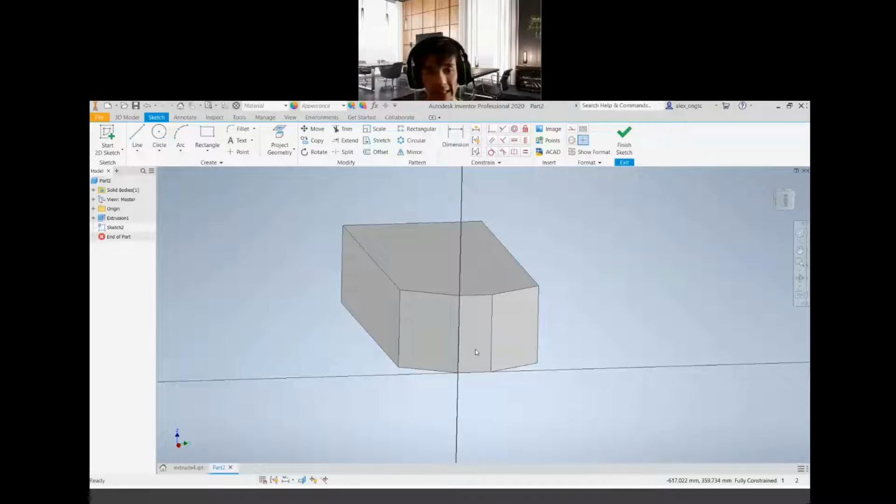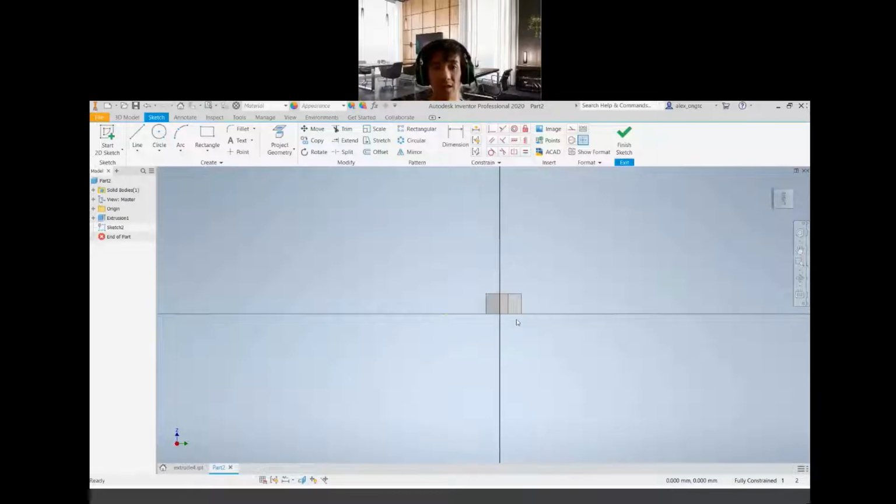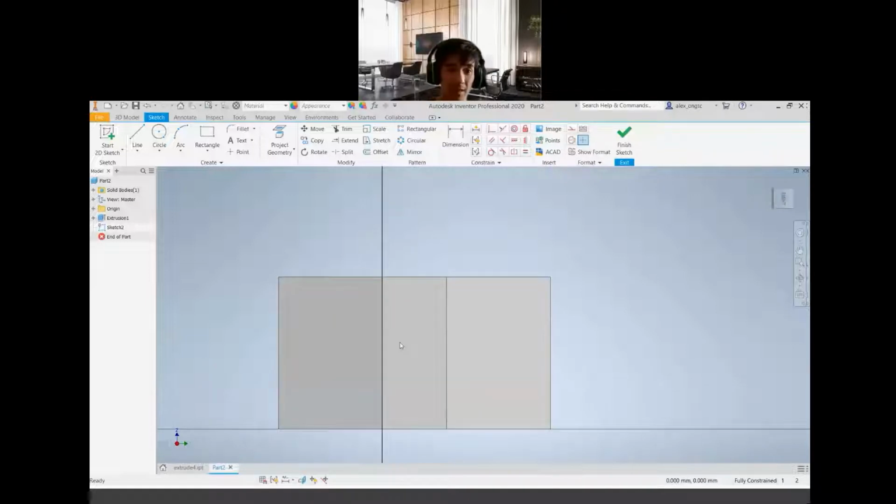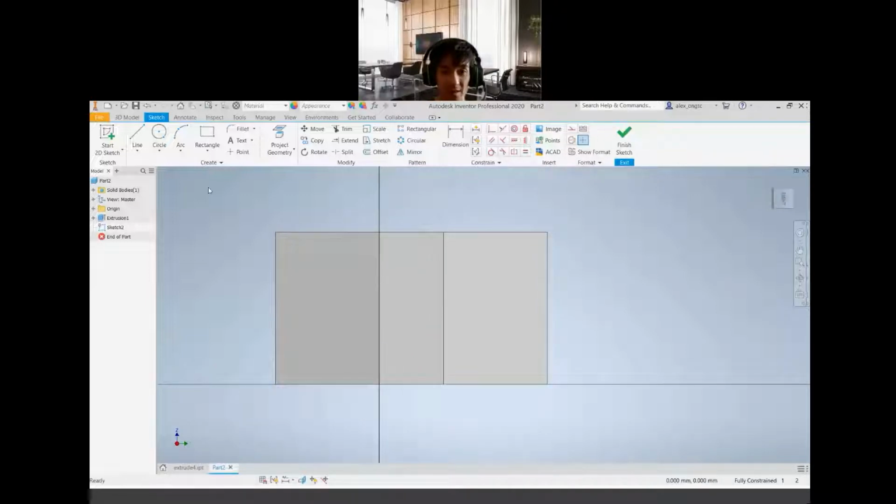If you get it right, the next thing is I would like you to create two rectangles, but in 2D, it must actually snap to this point here. Just have a look at what I do. I go 2 points here. Sometimes it will give me a reference, sometimes it doesn't give me any reference actually.